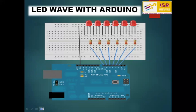Pin number 2 to 7 we have used, and the negative terminal of your LEDs, that is the cathode terminal, we have made common, and then we have connected all the cathodes of your LEDs to the ground of your Arduino board. I hope the circuit is clear and the connections are understood.